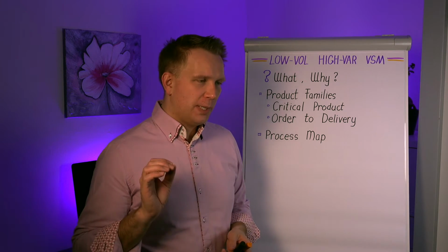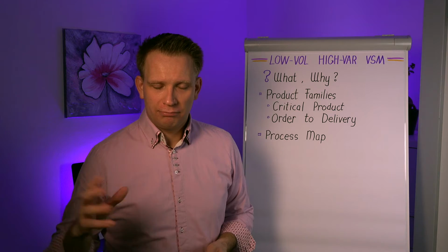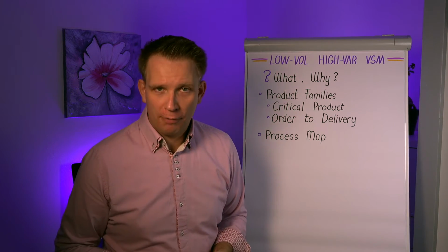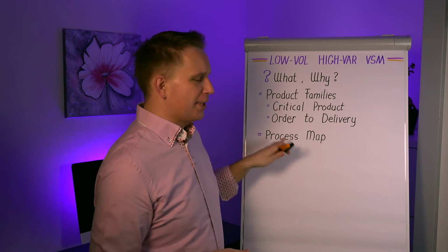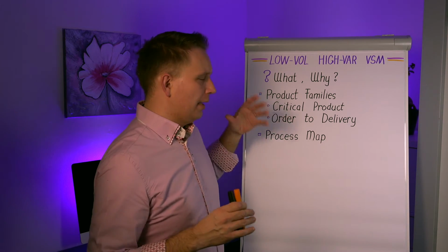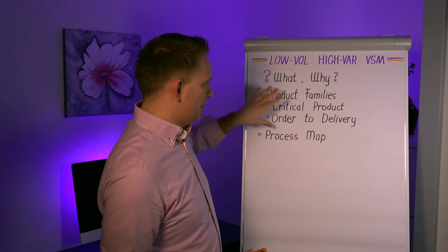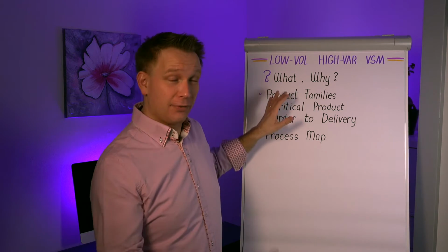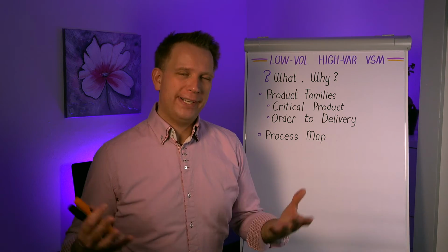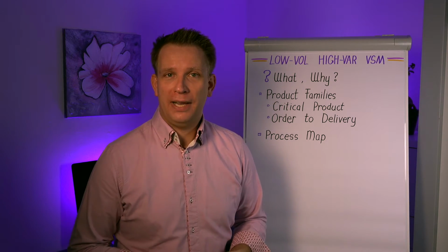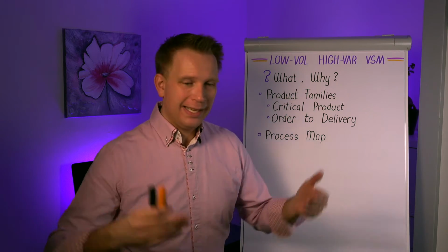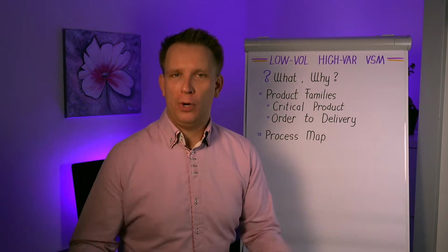When you want to do something that looks a bit more like a traditional value stream map in a more high volume type of manufacturing, you go to process mapping. This is interesting if you are not per se looking at the flow, the throughput of specific products, so delivery times to customers, but you are more looking at how we can increase the total output of our factory, or we have a couple of bottlenecks that just seem to be clogging up the whole factory, and this factory can do more, right?